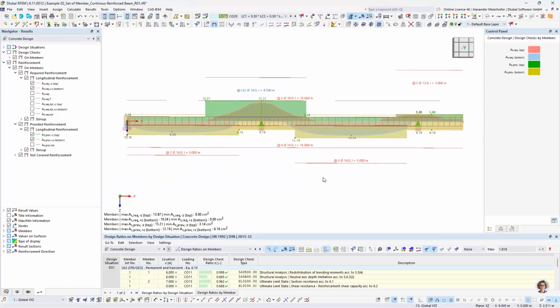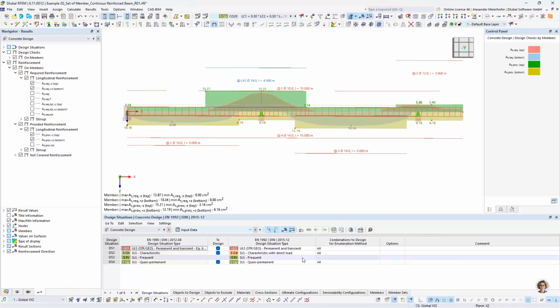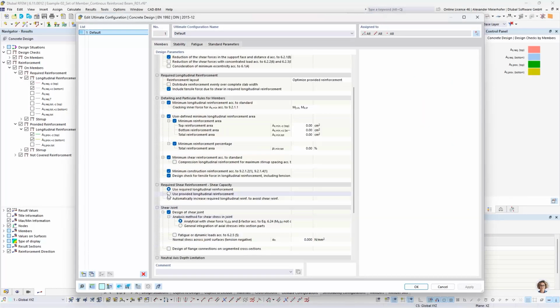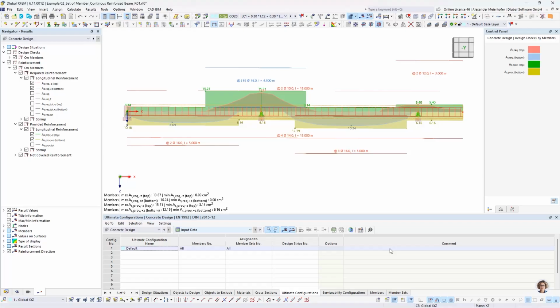one top feature for the beam design is that we can also use the net concrete cross-section area for highly reinforced sections. So this is also new, that you can remove the concrete area behind the rebars. If you have a very big reinforcement ratio in the cross-section, then you can deactivate the area behind the rebars in our configurations. Very simple, only in the configuration make the check and then it will be removed. And it's also assignable to each member.